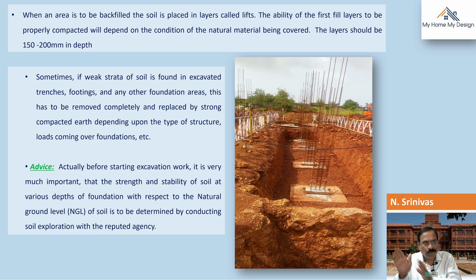It has to be removed separately, completely, and the soil which gives the field dry density, which gives maximum proctor density 95%, that type of soil is absolutely required for the filling purpose, backfilling purpose. The soil which gives this type of color, granular, has been completely removed and the new material has been filled here.